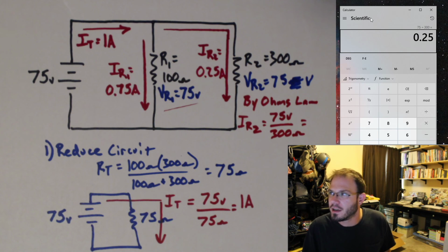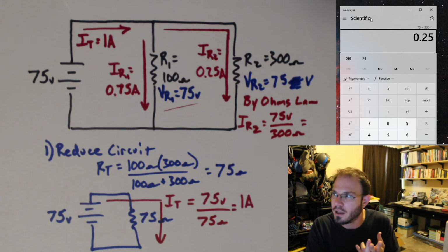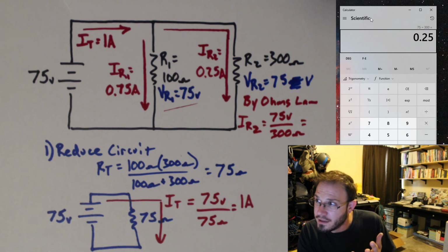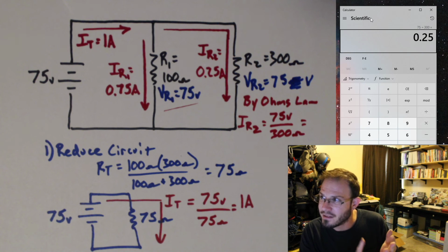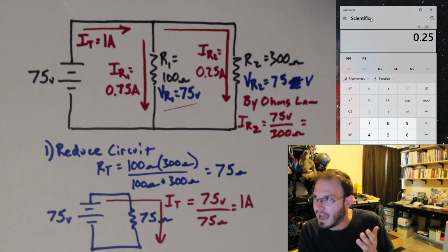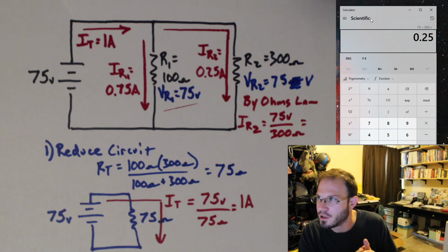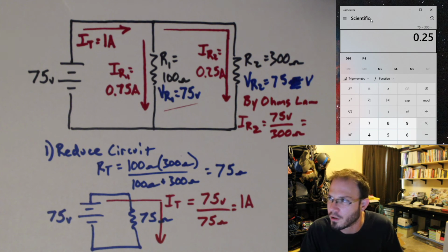We have covered series circuits, parallel circuits, Kirchhoff's voltage law, and Kirchhoff's current law. What else? Series resistance adds. Parallel resistance does the reciprocal inverse equation, or the more simplified multiply-over-sum for the two resistor case.